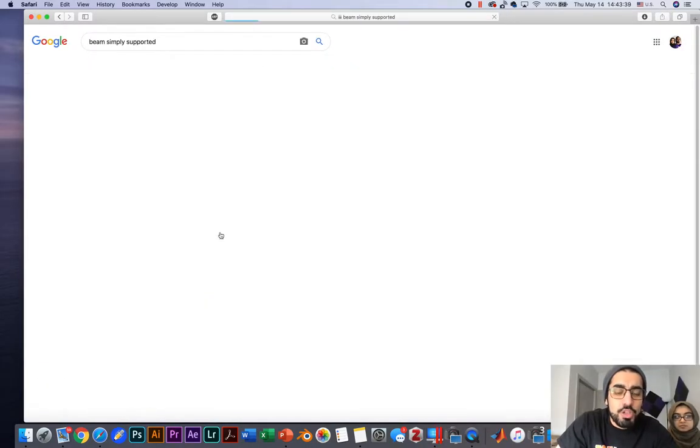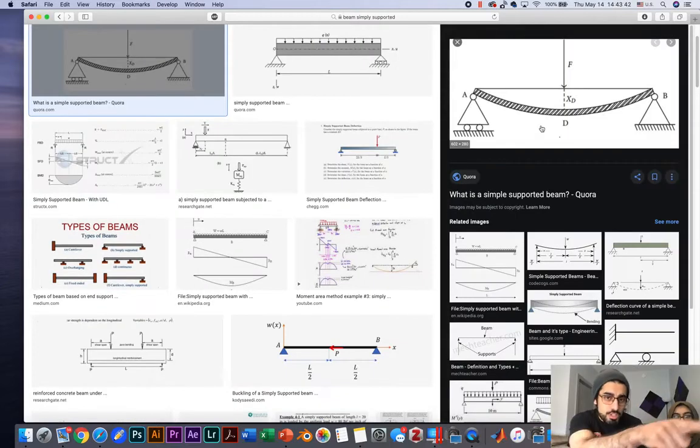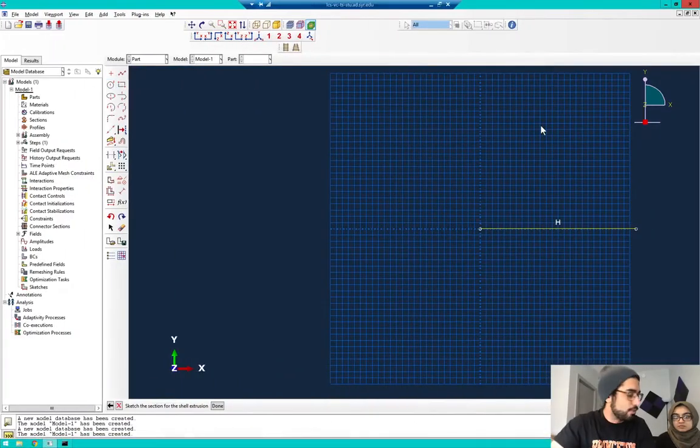when you draw the beam, how do you draw it? You just draw it as a line, right? You don't actually draw the cross section. And when you analyze it, you say, okay, what's the modulus of elasticity of this beam? What's the moment of inertia of this beam? But you don't actually draw the cross section. You just assign a moment of inertia to it without actually drawing it. So the same thing is followed here.